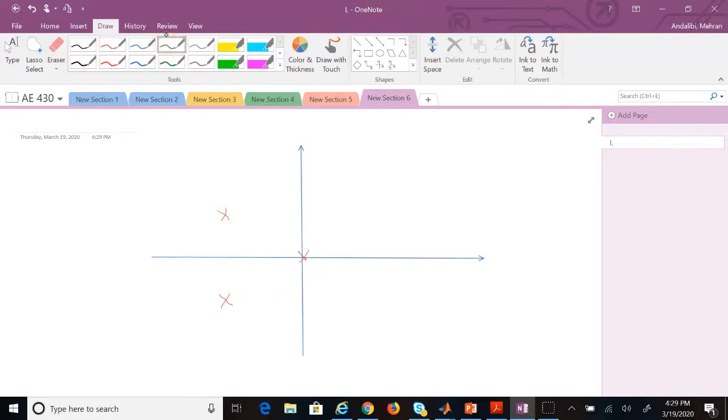So it says the angle is 180 minus the angle from the other poles, plus the angle from other zeros, but here we don't have any zero. So what is theta 1 and theta 2? So we connect these guys to P1 like this with these vectors, and then find their angles. So one of them is this angle, one of them is this one, right?